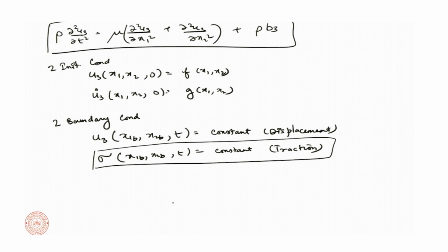We can include pre-stress, that is the membrane is stretched out tightly. However, in most cases our boundary conditions are displacement boundary conditions, that is the body is fixed at that point, which is the most common boundary condition.